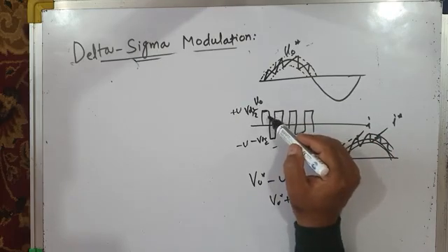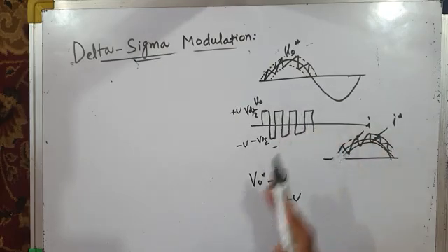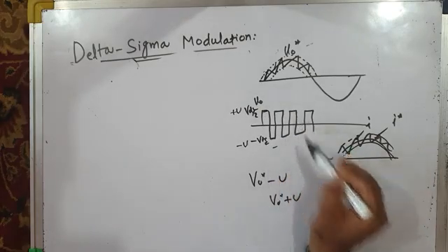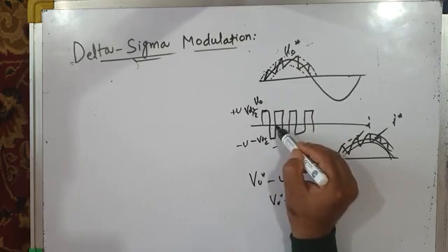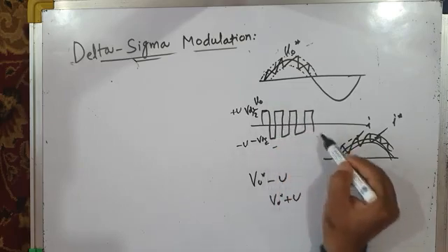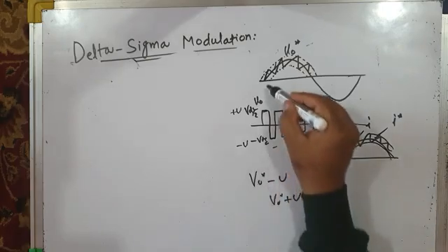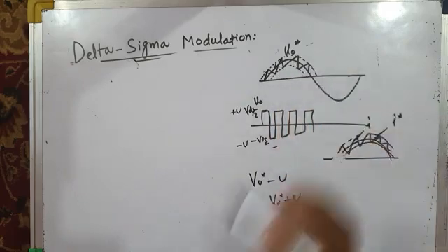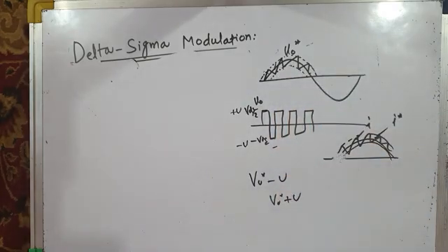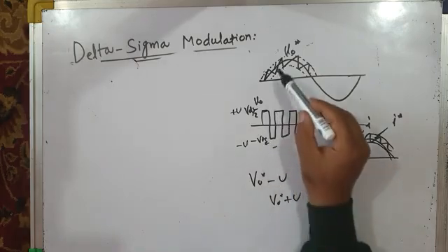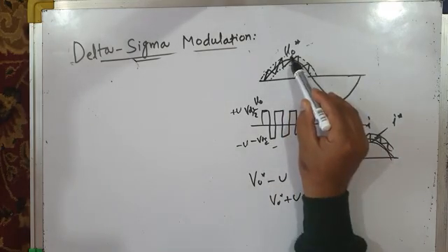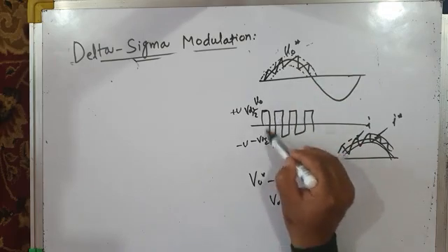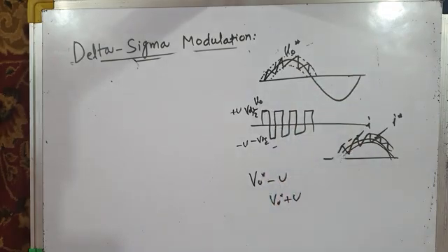But we know that in case of PWM voltage source inverters, our load voltage is in the form of switched voltage pulses like this, plus VDC by 2, minus VDC by 2, or plus VDC, 0, or minus VDC. It's a discrete signal, so it is not possible to create a hysteresis band and make this load voltage follow the reference load voltage like this. So that is the problem. In other words, you cannot subtract a continuously varying reference voltage signal V0 star from a discrete voltage like this. It's not possible. So does that mean that we cannot have direct control over voltage using hysteresis band?